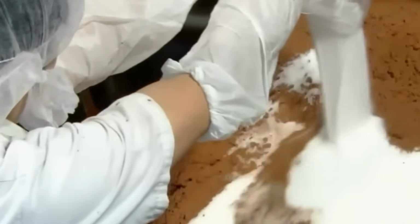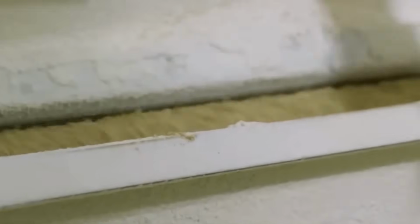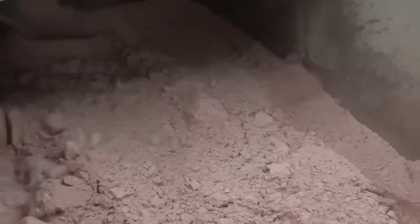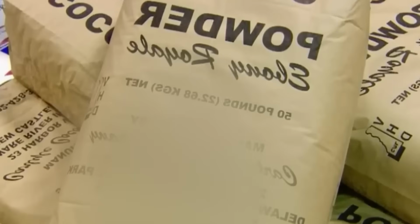Cream-filled rolls pass through a secondary cooling tunnel set to 10 degrees Celsius for 60 seconds to solidify the filling. Thermal imaging sensors confirm internal stabilization before exiting. At this stage, each roll is individually scanned for dimensional conformity, surface defects, and fill anomalies. Rolls not meeting target criteria for weight, symmetry, or visible cream containment are diverted via pneumatic actuators into separate waste chutes. Approved rolls proceed to flow wrapping.